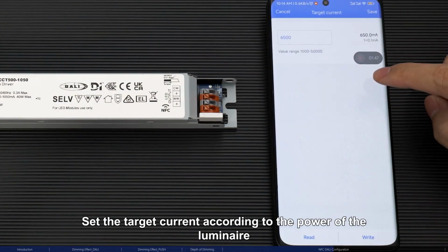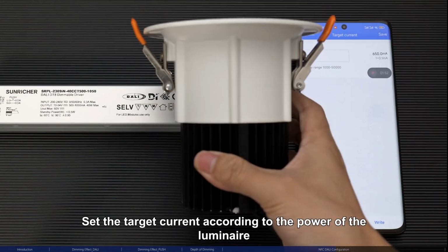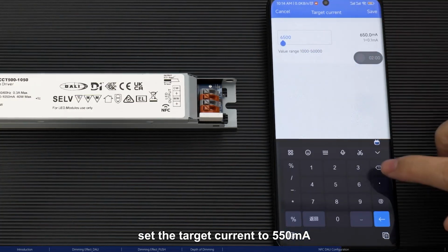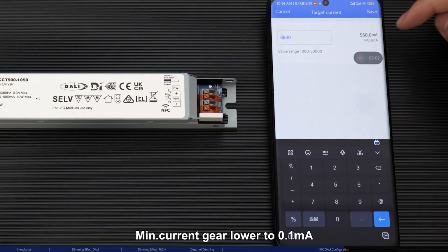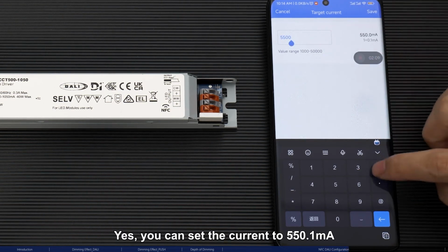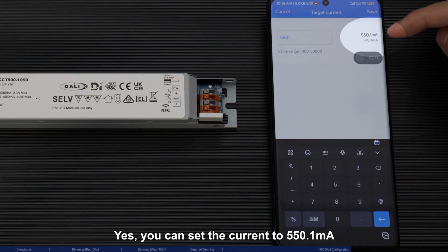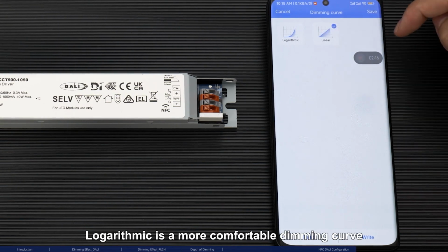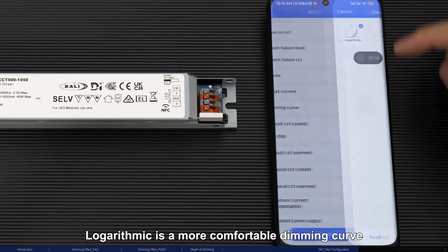Target current, set the target current according to the power of the luminaire. For example, for a 30 watts lamp, set the target current to 550 milliamperes. Min current gear lower to 0.1 milliamperes. Yes, you can set the current to 550.1 mA. Dimming curve, linear or logarithmic selectable. Logarithmic is a more comfortable dimming curve.